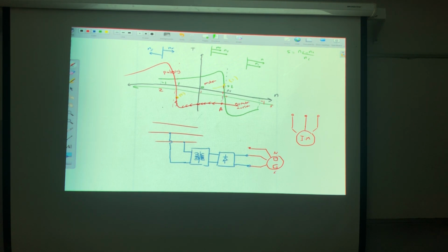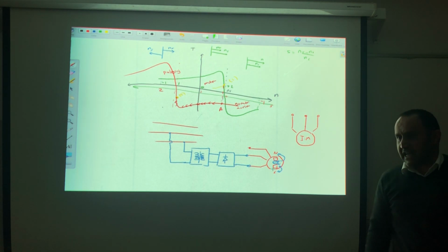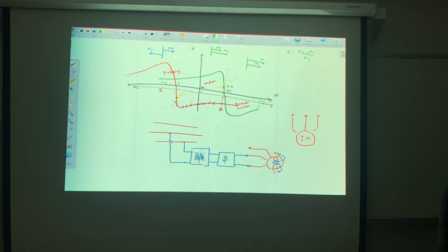Then the rotor also will generate two poles, and this will be the south, this will be the north. The south will catch the north, the north will catch the south, and they live happily ever after. So, yes, this is dynamic braking. It's very, very fast to brake the machine. Good.